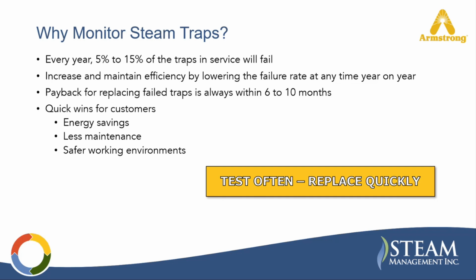Many customers don't realize this, but failed traps often contribute to the premature failure of nearby traps. A healthy system tends to stay healthy, and an unhealthy system often creates a cycle that leads to additional failures. Another important point is that most steam traps cost significantly less to replace than the losses they create when they fail.